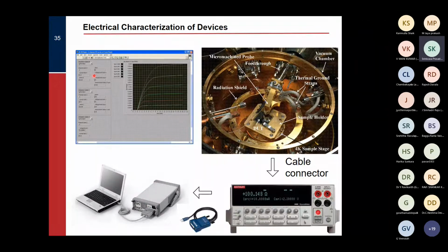So here, for example, this is a simple IV script which is measured with LabVIEW. What you do is that you have these parameters which you put here, like what is the initial voltage, final voltage, step size, number of cycles, etc. And here you can see that this measurement is being done. This is like an IV characteristics of a field effect transistor. Here you can see for different gate voltages, you get different kinds of these graphs. So that measurement can be done.